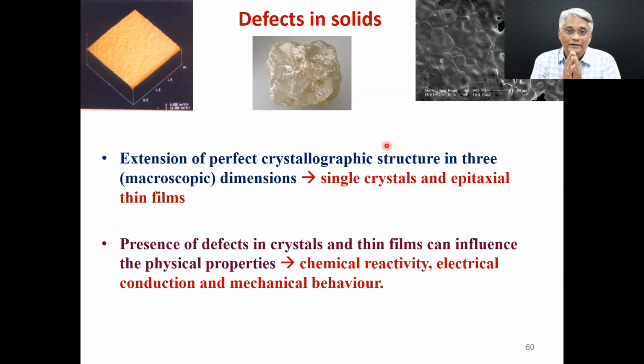So I need a certain amount of temperature for the incoming atoms onto the substrate to form a crystalline growth here. But if I'm not providing enough thermal energy to the substrate to create the so-called adatom mobility for the atoms to go around and find their lattice positions, if the substrate is not heated, no thermal energy is given to the incoming atoms, what will happen is these atoms start agglomerating and leading to the formation of islands, and that's where you see a polycrystalline film.